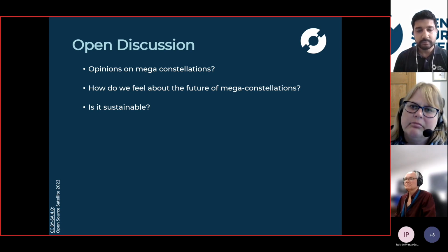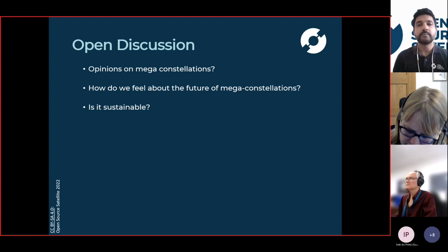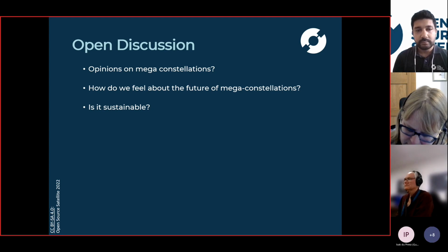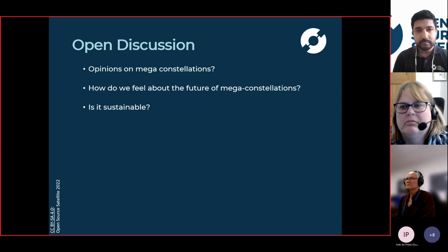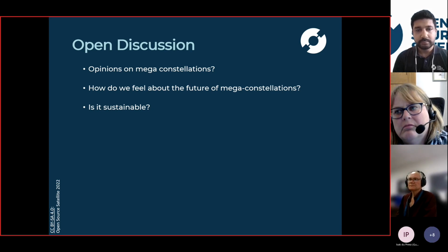So we discussed at that meeting 2 different types of orbits for educational, amateur, and scientific payloads. And the one that's probably the most relevant here would be a modified HEO. So instead of trying to fight it out at LEO, you have a highly elliptical orbit, and then you raise the lower altitude to not cross over any of the constellations. The FCC was enthusiastic about this. The repercussions are that you will have a higher delta V. It's a little more challenging, but with the reduced mission time and all that, the 2 things may not be conflicting.